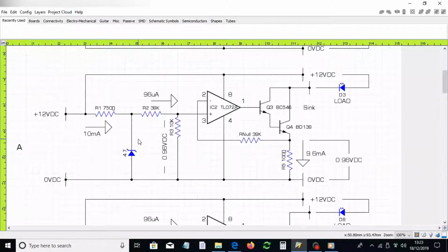So what I'm going to do here with this instrument doesn't really warrant a really high performance, expensive reference chip. I've got economics in mind, but I do need to replace the Zener diode. I need to get its voltage down to say 2.5 volts, something like that, so that I can drop the compliance voltage down below 5 volts. So I'm looking at replacing this Zener diode, and that's what I'll do next. I'll show you my idea and my chosen device in a second.